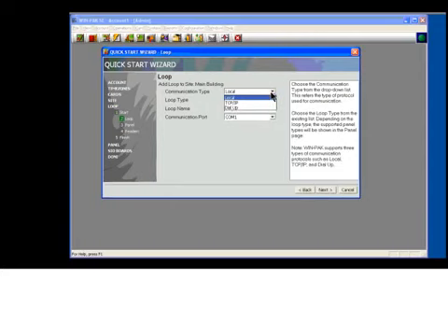And we'll have to select what type of loop. Now, we've got a choice. We can use a direct RS-232 connection, we can use a TCP/IP connection, or we can use a dial-up connection. In this case, we're coming physically out of the back of our network card over the Internet, and from the Internet directly to our panel. So we're going to be using a TCP/IP connection.